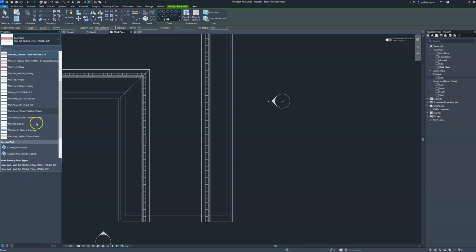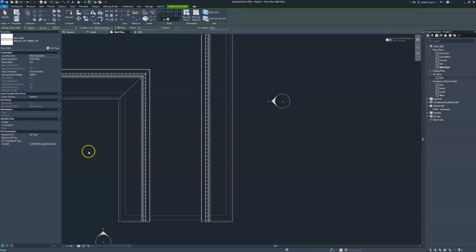I'm going to make it a 100 partition wall, plasterboard 75, and let's do a block. Let's do a block wall. No, let's do stud. It doesn't really matter actually. Very indecisive. Doesn't really matter what we do. So let's just go with the block. Okay. So I'm going to do a dormer. Let's say it's going to come out here and it's going to come quite far and then back in and roughly to there.